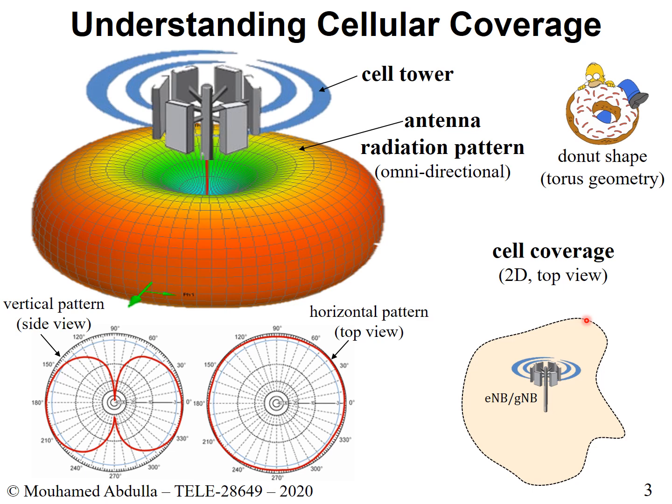So these are the different reasons why you'll end up with a shape like this. This radiation is shown because you are looking at the radiation of an antenna in a situation where the earth is flat and there's nothing else. There's no obstacles, there's nothing. This is how the radiation looks. But if you put your antenna in a city, in a certain environment, there's buildings, people, cars, different objects and variable elements around you, then you'll end up with a coverage that looks more or less like this.